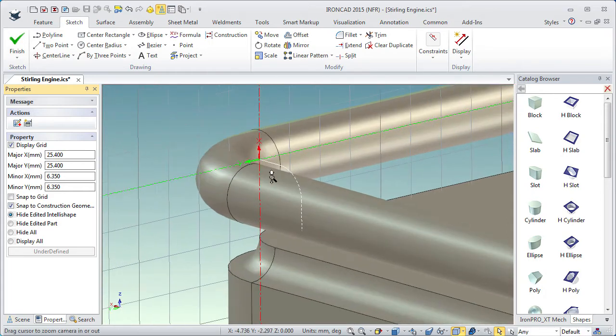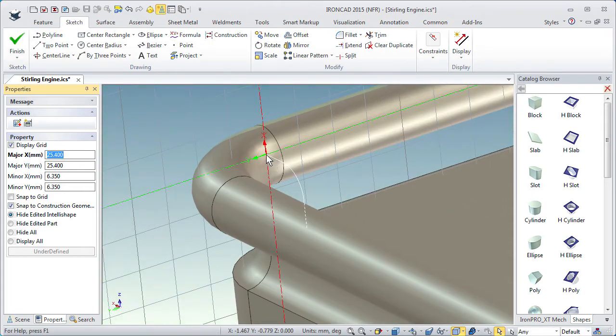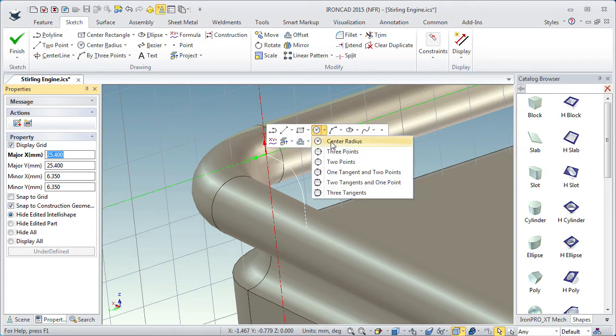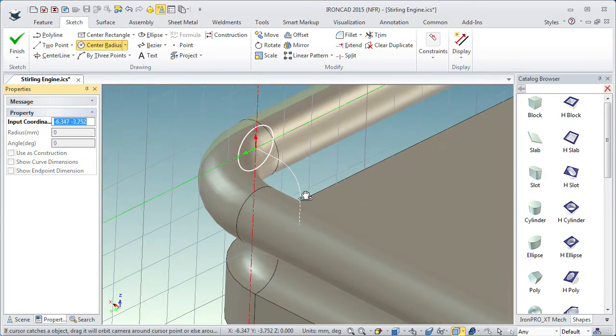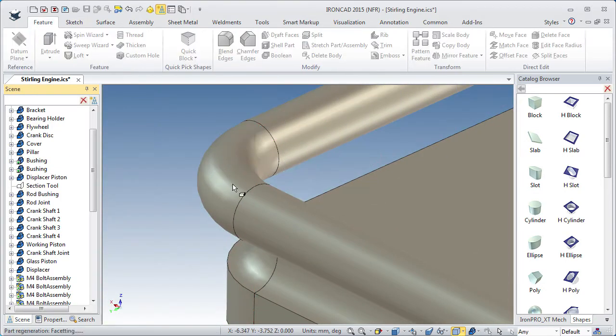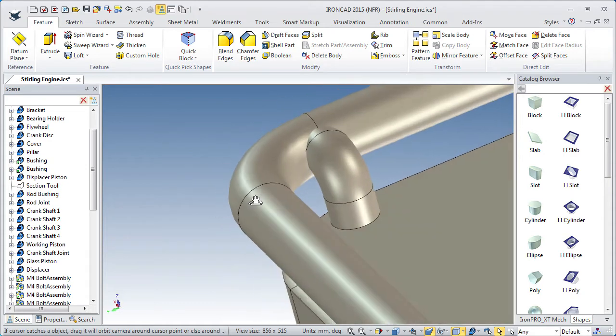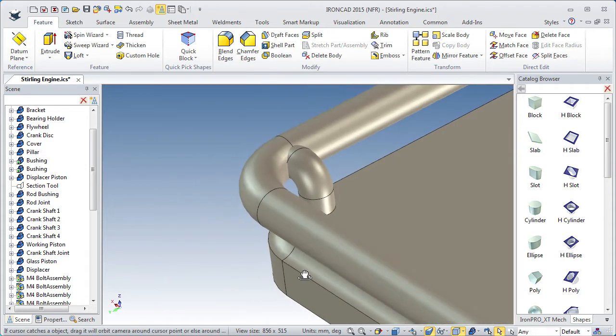and I will draw a circle. That will be the shape. So I will turn on my menu, press S, select circle, and click the origin. I drag a bit, and I will type 4 and hit enter. Then I will click finish, and we got our first support for the railing.